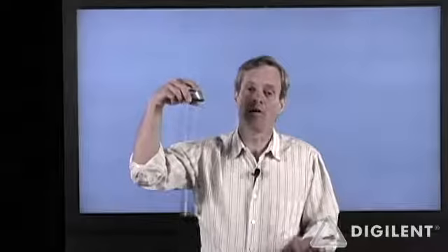We can also consider our slinky to potentially be a time-varying system. If I'm operating this slinky, bouncing it around, and I decide to change, for example, the temperature on a regular schedule, the physical parameters of this slinky, like the Young's modulus, which contributes to the spring rate of the slinky, may change as I change the temperature. I'd have to change the temperature quite a lot, granted, but I could make them change. If the temperature is changing as a function of time, it may look like the slinky's parameters are changing as a function of time. The resulting governing equations would now be differential equations with time-varying coefficients.